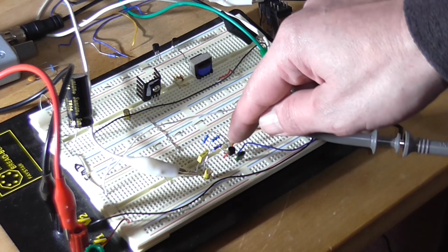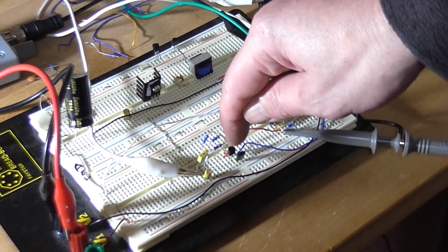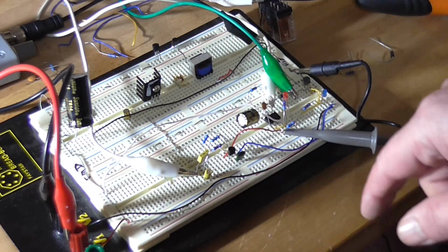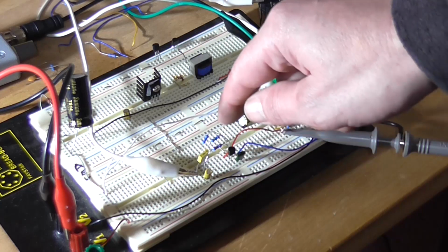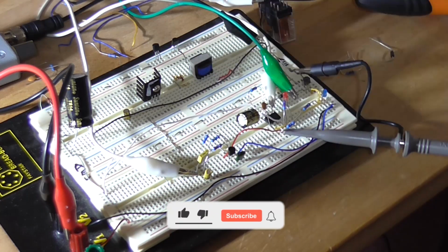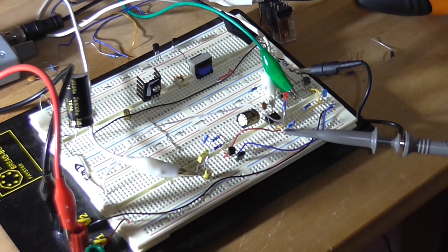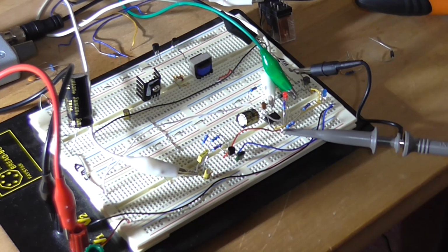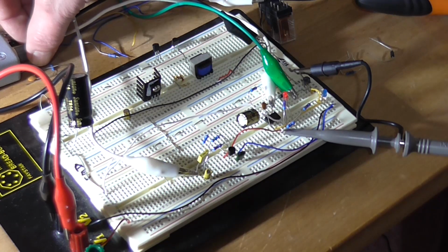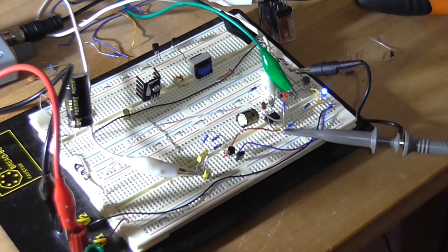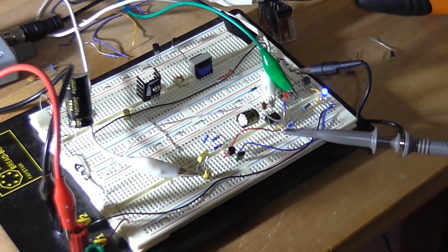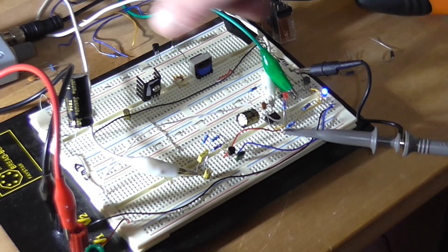I have, from the collector to the base of this transistor, a 1 megaohm resistor as negative feedback. And the input resistor that goes between the capacitor and ground here is also 100K. And now it takes very little input signal to trip the circuit. So I'll turn the circuit on, we're in standby, and if I slowly rotate the pot, bam. And we're only probably at the 8 o'clock position on that particular pot on the attenuator.